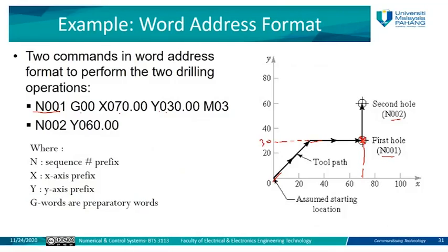I want this to perform a task here, for drilling and so on. Later on, we will see how to give the command for this. But now we want just to draw the path for this machine, or for this spindle. Let's go to this point, then, which is 30 on the y-axis and 70 on the x-axis.